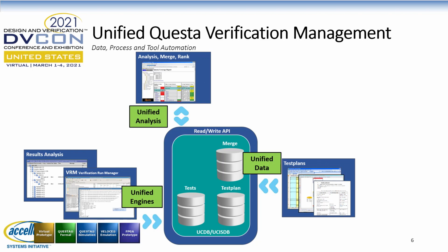I asked them what caused them to start using a verification plan, and they told me that on their previous chip, in all the simulations they did, they never simulated sending 2 packets in a row. Of course, when the chip came back and they plugged it in, it tried to send 2 packets in a row, and the chip hung. So now the first thing in every verification plan of theirs is send 2 packets in a row, and then they go on and test other things.